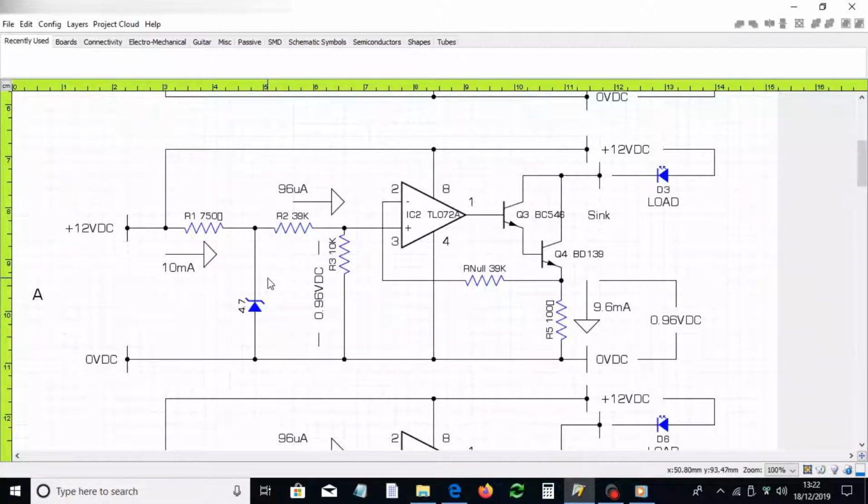They used a chemical cell that was stable, but there were one or two disadvantages with it, quite significant. One is that it takes time for them to physically settle, so if you move the instrument, the voltage won't stabilize until maybe an hour later.